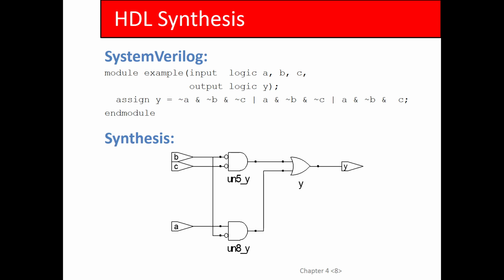So they minimized it. They ran this through, did they do a Karnaugh map? Probably not. They used an algorithm called Quine-McCluskey, which is kind of an iterative heuristic that tries to solve the Karnaugh map for an arbitrary number of inputs. Not necessarily optimal, though, because that would be NP-complete.